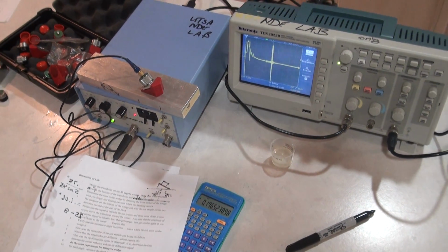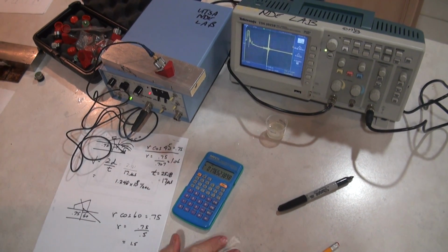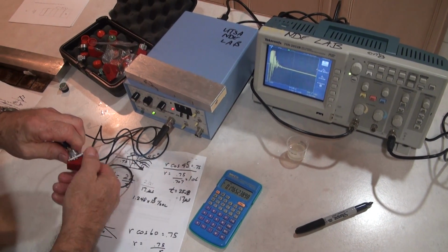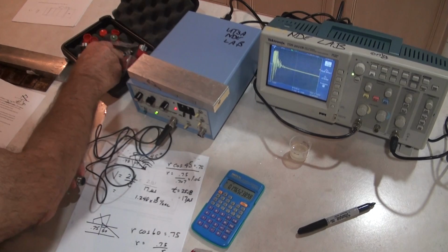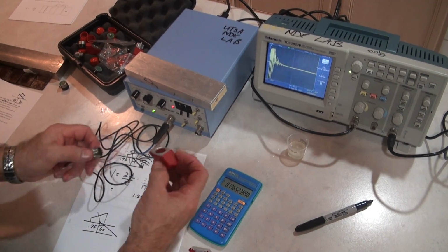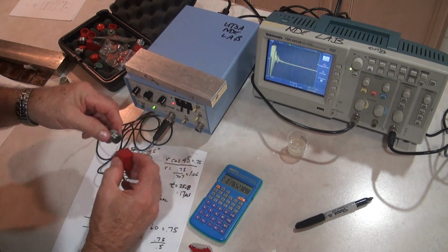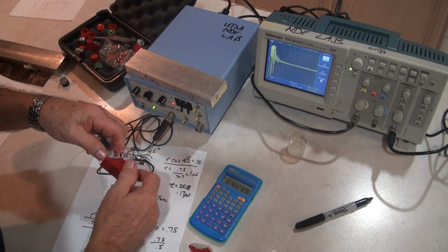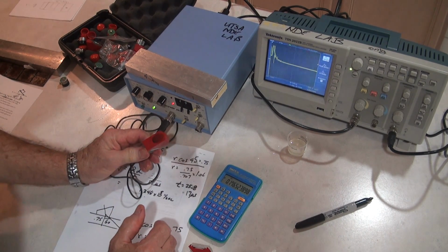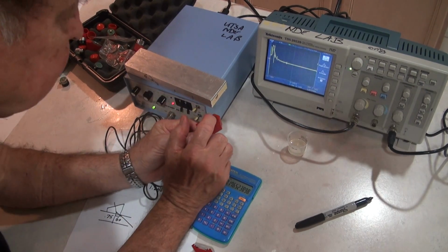Now what if we want to go with a 60-degree angle instead of 45? So let me pull that wedge out. Okay, now we have a 60-degree wedge, which is a higher angle. Again, I need to couple my transducer to the wedge. The first thing we want to do is figure out how much time it's in the wedge, so I'm going to do this again.